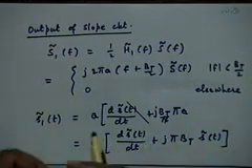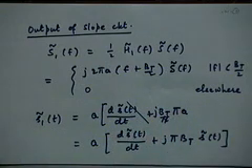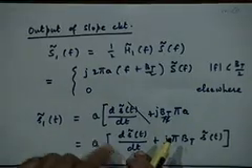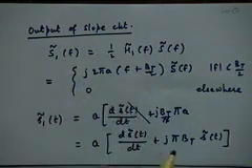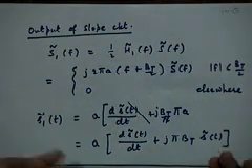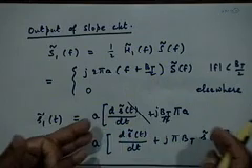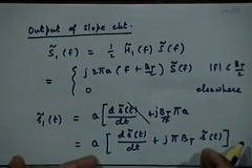Sometimes even though the envelope variations themselves may be small, the rate of variation, the derivative, may be quite large, and they can get accentuated. So your output in that case will be proportional not only to m(t), as it should turn out to be, because this entire theory was based on the assumption that the input signal had a constant amplitude.